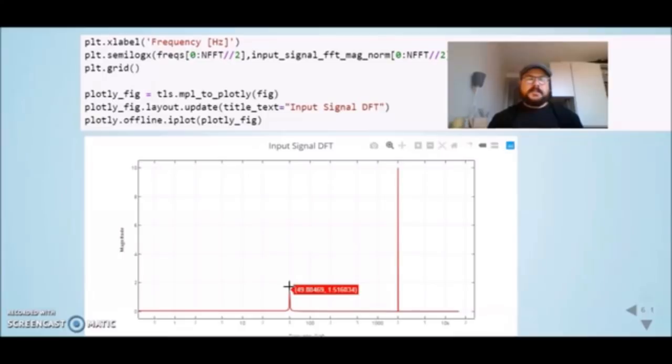The FFT has a limited number of FFT points, and depending on where your frequency is located, maybe it's not in the center of the bin, but in the middle of two bins, and we have this error in amplitude. So bear in mind that when we don't have any window, we are in fact using a rectangular window, and the rectangular window has certain characteristics in frequency.